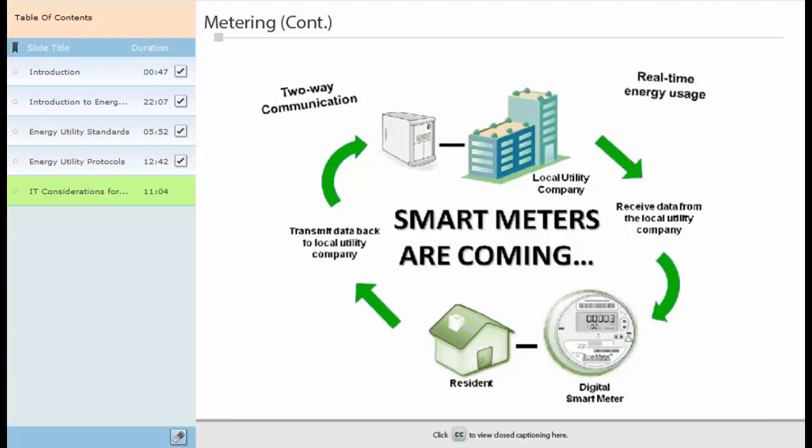Smart meters are developed largely to meet utility needs and the increasing sophistication of the distribution grid. Smart meters are focused on the big picture. In many cases, these meters satisfy the legislative mandates of interval data and remote communications. However, beyond that, their capabilities focus on utility infrastructure needs and grid interconnect. Smart meters focus on providing utility with time-differentiated energy use. A large driver in smart meter technology is a need to capture and report interval energy use for demand response programs and expected time of use pricing rate structures. Additional utility applications include remote meter reading applications and service connection and disconnection abilities.